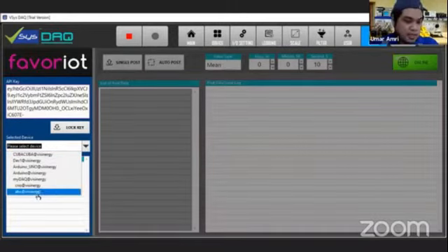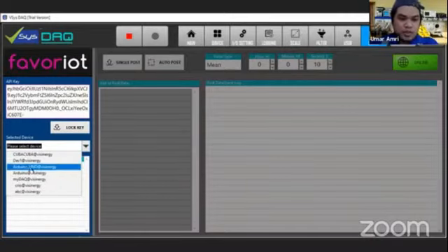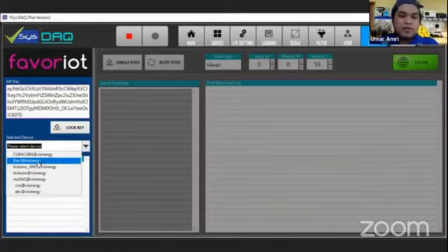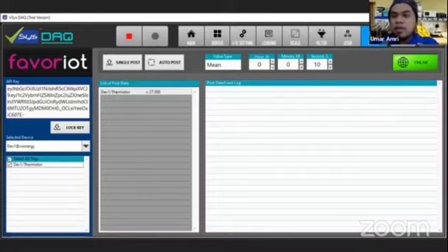You can see there's a lot of devices that I created for testing, Cuba-Cuba, Arduino Uno, and so forth. Okay, so I'm using device1 at VSysDAQ. I just click device1 at VSysDAQ, and I click device1 at /Thermistor. So this is the only data that I want to push to the cloud platform now. Okay, so device1 Thermistor reads 27.65 degrees Celsius. So I want to push that.